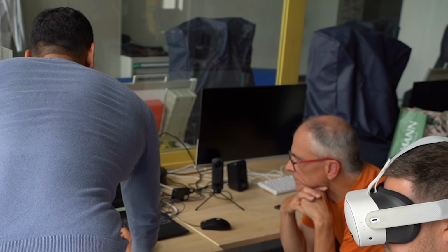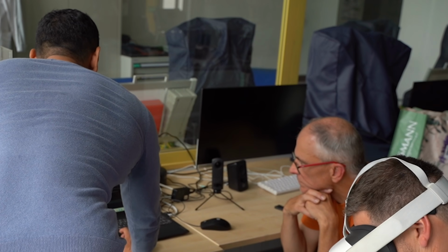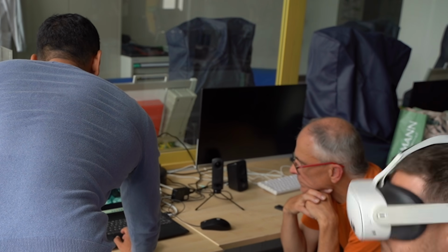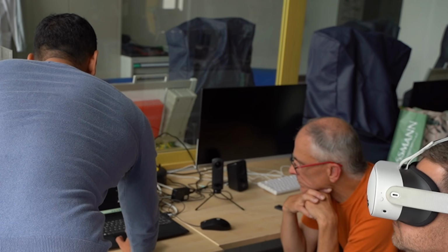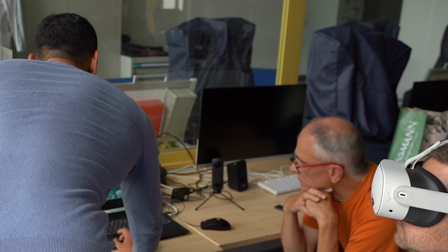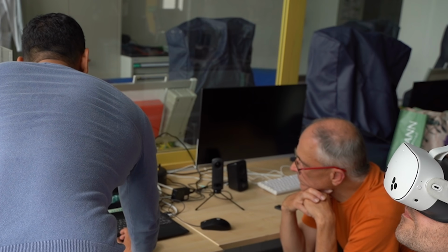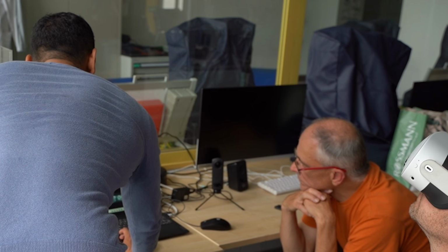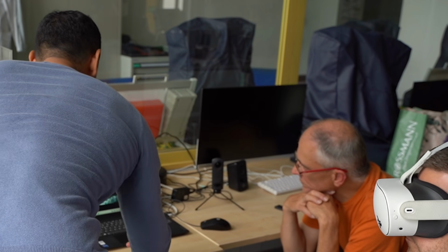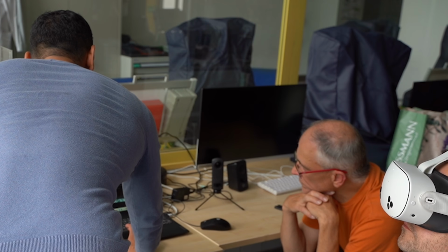Now we begin with practice, finally: how to operate the heating cycle. So safety first, confirm that this lamp, which is in here, and we tell them which lamp it is, this one, B3, is turned on, because this means that the sensor is detecting water. And now you can press the HS4 button, which is the start button, and with this the pump M4 will begin to work, like right now.